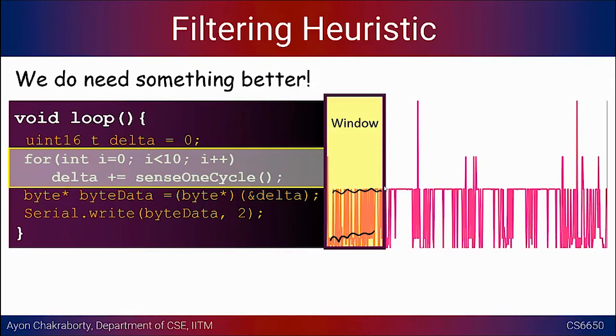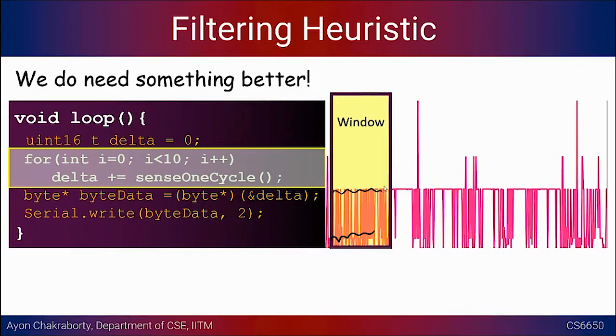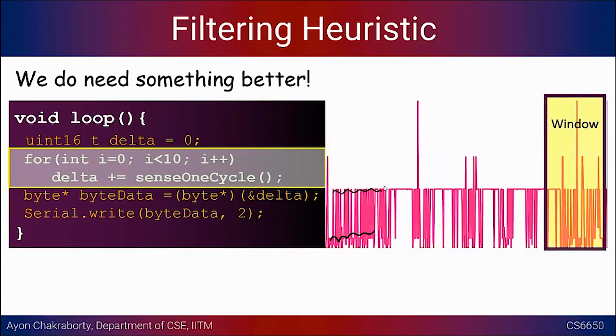So it's better to concentrate on a small time window and look at how the statistics of those values change, to get a better calibration and make event detection much more efficient. Again, this will be a sliding window, as many of you have already implemented such techniques for heartbeat detection.